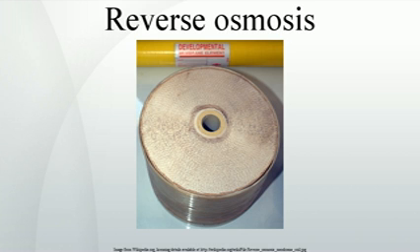In some systems, the carbon pre-filter is omitted, and cellulose triacetate membrane is used. The cellulose triacetate membrane is prone to rotting unless protected by chlorinated water, while the thin-film composite membrane is prone to breaking down under the influence of chlorine. In cellulose triacetate membrane systems, a carbon post-filter is needed to remove chlorine from the final product, water.